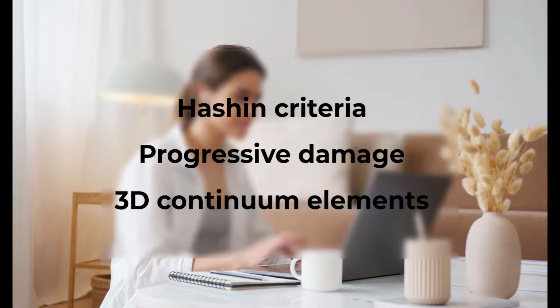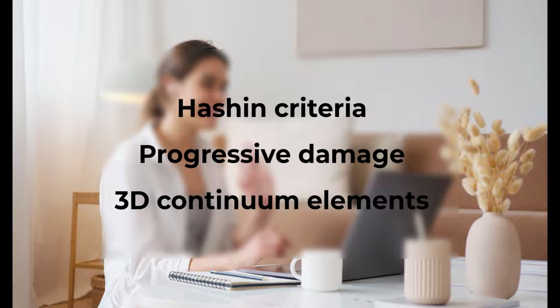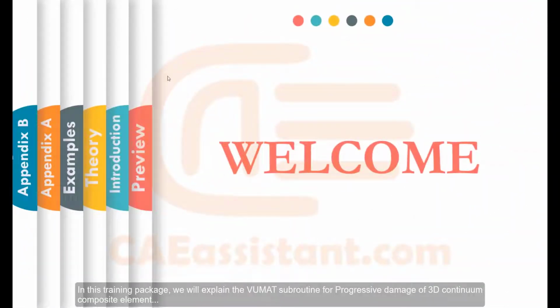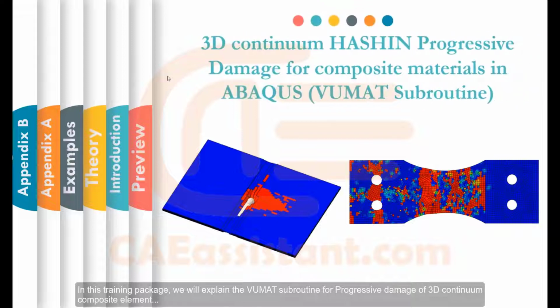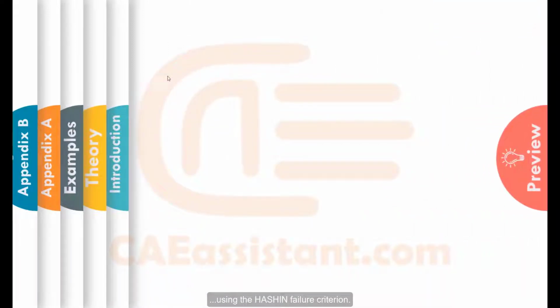Do you know how to use Hashin criteria to model progressive damage in 3D continuum composite materials? Let's find out in this video. In this training package, we will explain the VUMAT subroutine for progressive damage of 3D continuum composite element using the Hashin failure criterion.